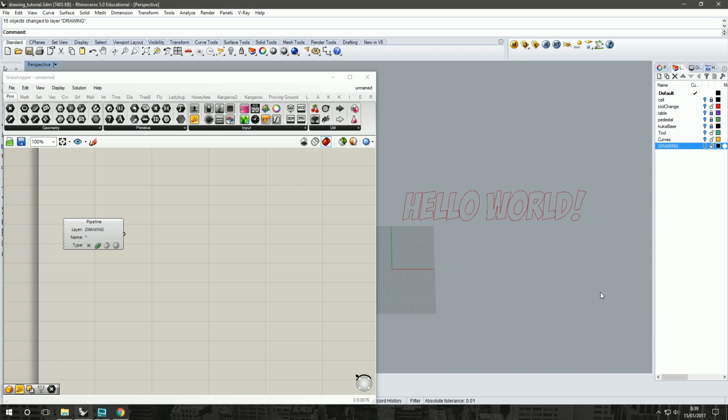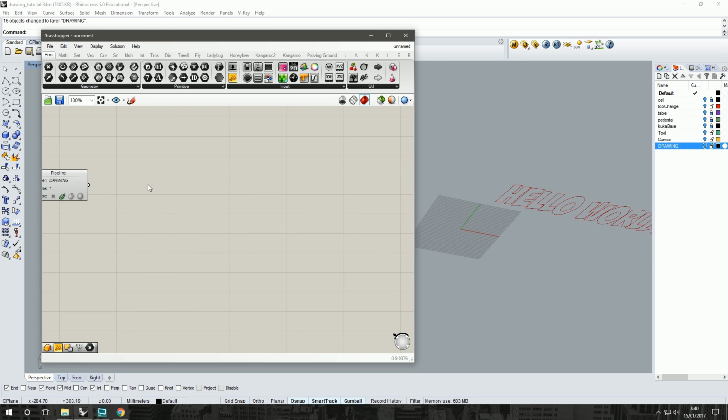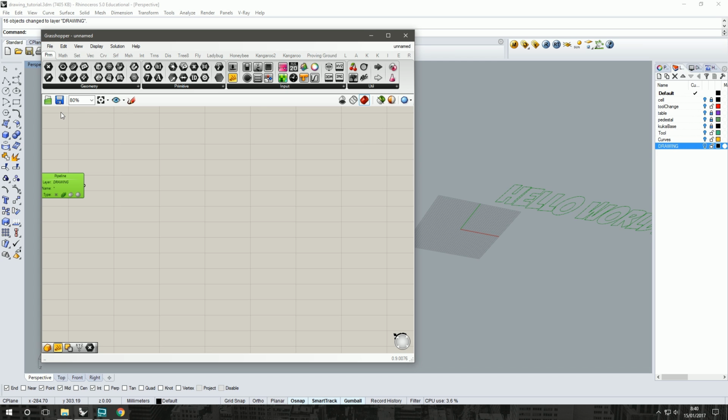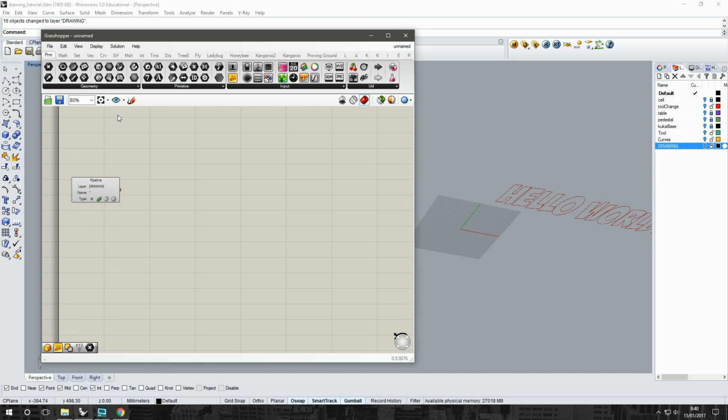Now I know the canvas that we're working with is 1 meter in X and 600 wide. So that has been imported based on 0, 0, 0 in the Rhino Cartesian space, which is exactly what we wanted. So that's just on ground level in the cell. But that's not where we want to draw. What we're going to do is we're going to set up a custom area for it to orientate the curves that we import and then to draw. And that way all we ever have to do is change the curves that are imported on our layer, go from there.